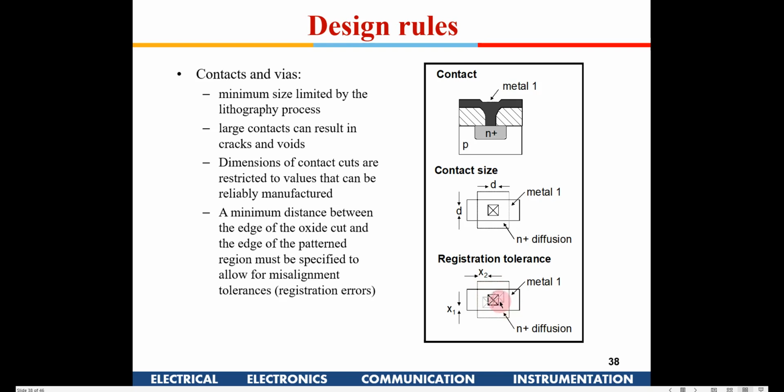So when we call for an NMOS or a PMOS in the schematic, we take the PMOS layout. We are not going to draw the PMOS starting from the active region, and all these small issues will be taken care of. All that we need to focus on is the interconnection. That is what VLSI engineers generally do.